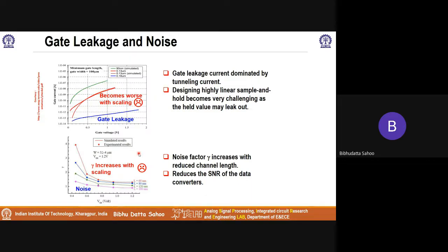especially in some systems like DAC designs, where one bias node is biasing a ton of transistors, is the gate leakage. What happens is that the gate leakage results in the voltage going to each and every transistor being different. Ideally, you want the same bias voltage to go to all of them. But since it is connected to a lot of gates, each gate has a leakage current, and thereby our voltage drops as it goes to different transistors. So in our DACs, there is a huge amount of variation in the current flowing through the individual current sources, and that is very, very detrimental.